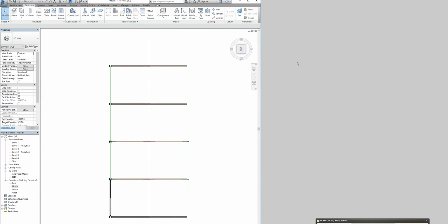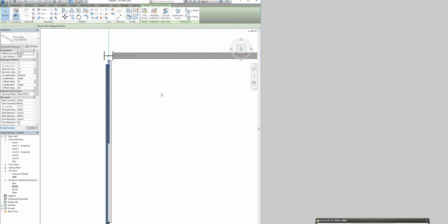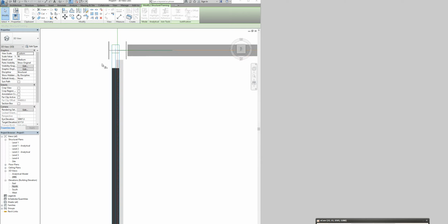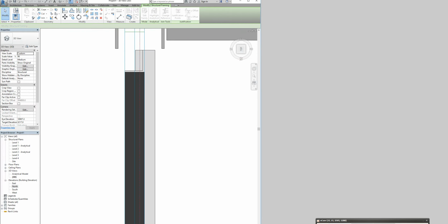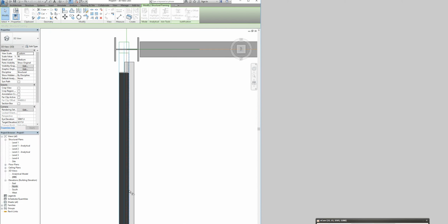Right. To correct the brace intersection, select one brace. I select this brace. And go to justification points. I see that's the icon. It's here. All right. Select the outer corner line. So we got many lines here. We got this line, this line. So the outer will be the furthest. This one is on the edge. So align bracing to the edge, outer corner line will be this one, right?